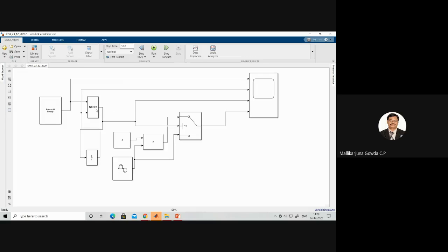Hope this is clear. So the XNOR output is connected as input to the delay element. The output of the delay element is connected as input to the XNOR gate. I wanted to see that also. So four things. The first window is binary data. The second window is the delay element. The third one is the output of XNOR. And the fourth one is my DPSK signal. Okay.